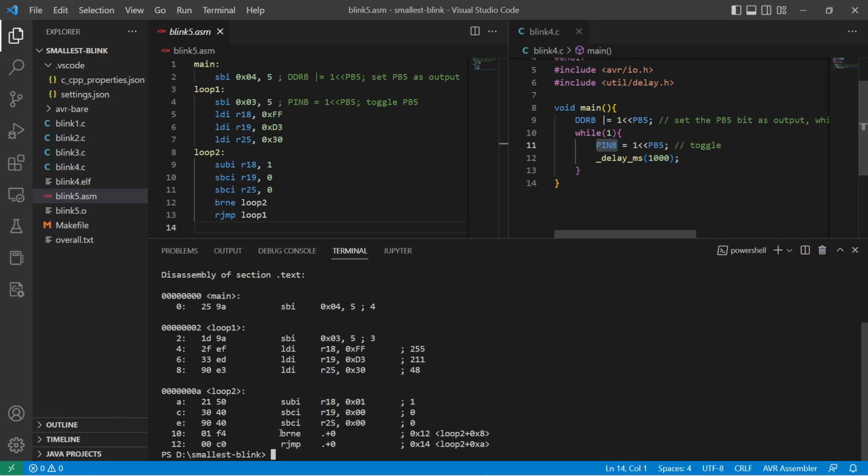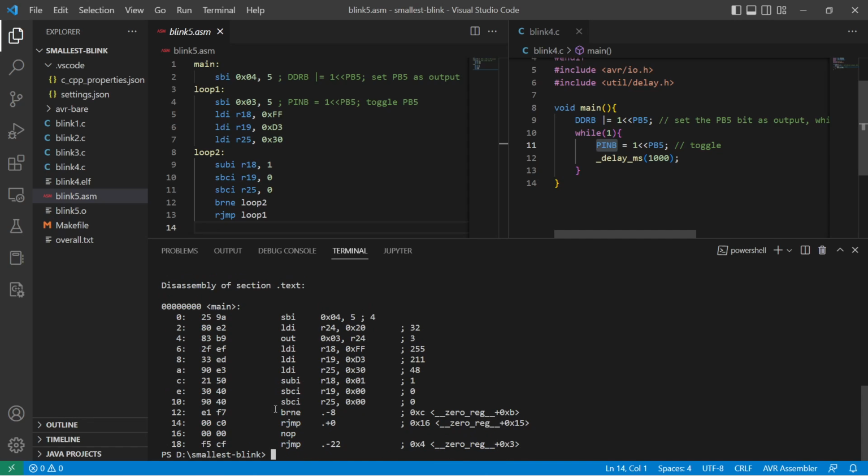We can see that the branch instructions are not branching to anything. They are just branching to zeros, both of them, which means the addresses haven't been known yet. Does that make sense to you? But if we disassemble the blink4.elf, we can see that we are jumping to something useful.